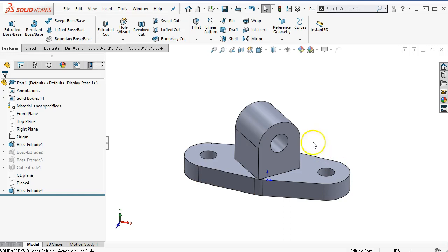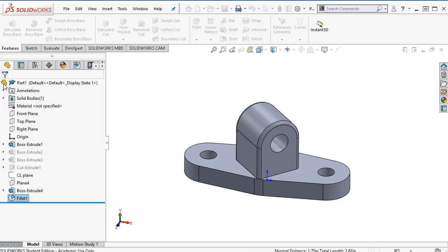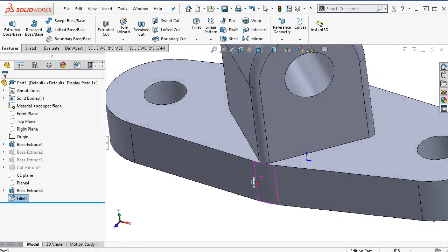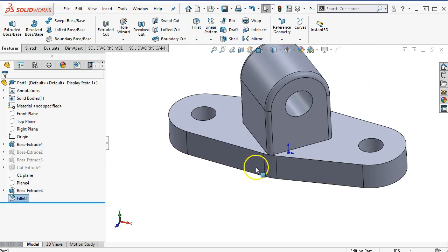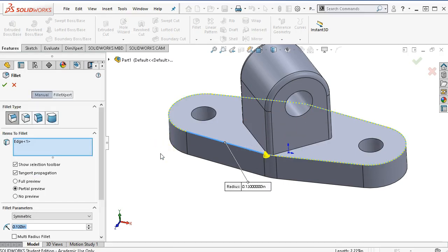All right, our radiuses, fillets and rounds of 0.12. I'm going to want to apply to the top first fillet 0.12. And then we'll accept. And where this comes up so close, this is going to be an interesting location for the radius. So we'll go around, and I still want to go with the edges first. So we'll see what it finds with the tangent edge. And then if I also include the base, we're going to see if this gets too complicated.